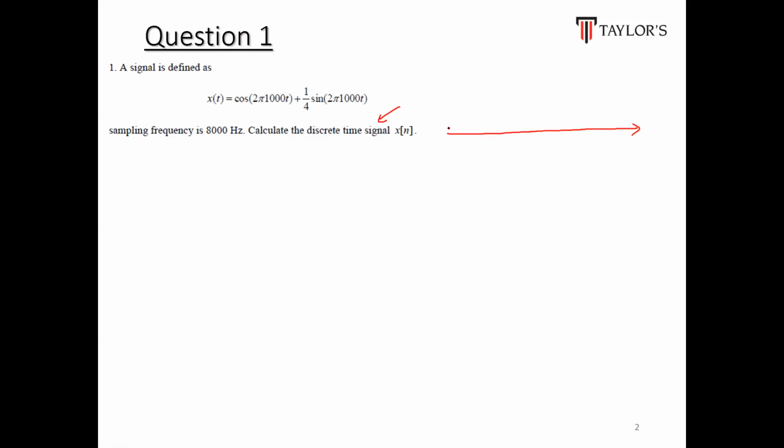Let's say I have a time signal that looks like this, like a sine wave. This sine wave tells me that this is at time t equals 0, this is at time t equals 1, this t equals 2, this t equals 3. And now I'm telling you that I'm sampling this particular sine wave with a sampling rate of 10 hertz. 10 hertz meaning that every 1 second, I have 10 samples.